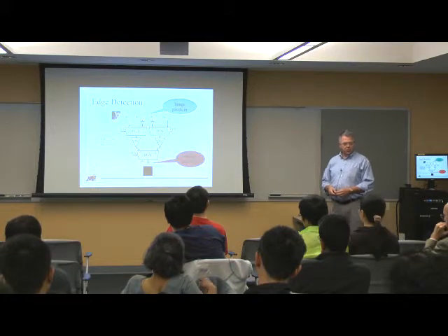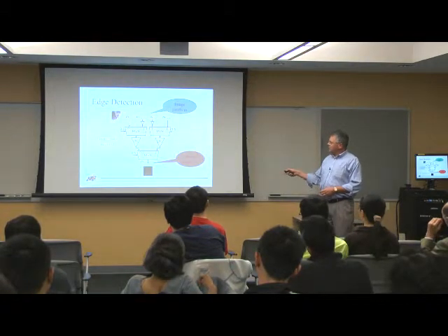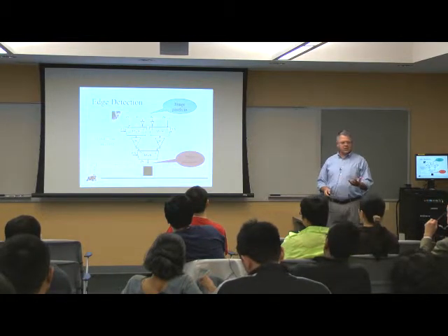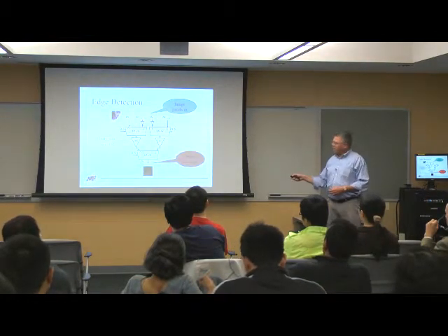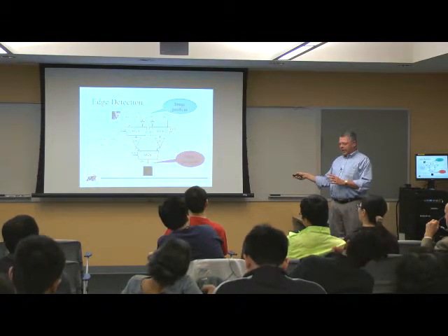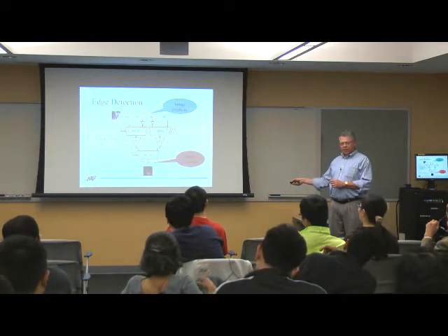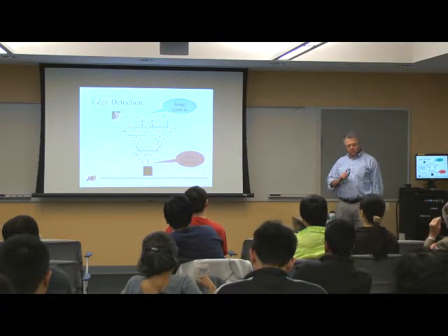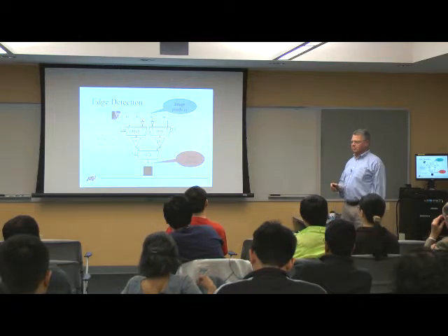And we've been looking at some circuits recently where we can detect directly in a stochastic domain, basically using sigma delta converters. And I can do an analog to digital conversion from analog to stochastic and then back to an analog value here without doing this binary translation in the middle. We don't have that fully worked out yet, but we're close.